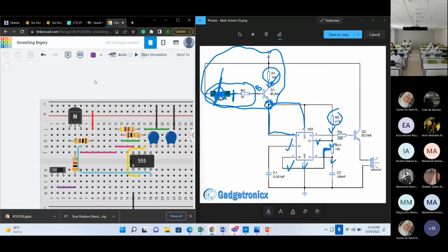Okay. Are you all done? Doctor, you can repeat the last step? Yes. Now what I need to do is to add the sensor. And I said that we're replacing the sensor with a switch because we don't have a sensor in Tinkercad. Now the switch has what? It has three different terminals: the common terminal, terminal 2, and terminal 1.